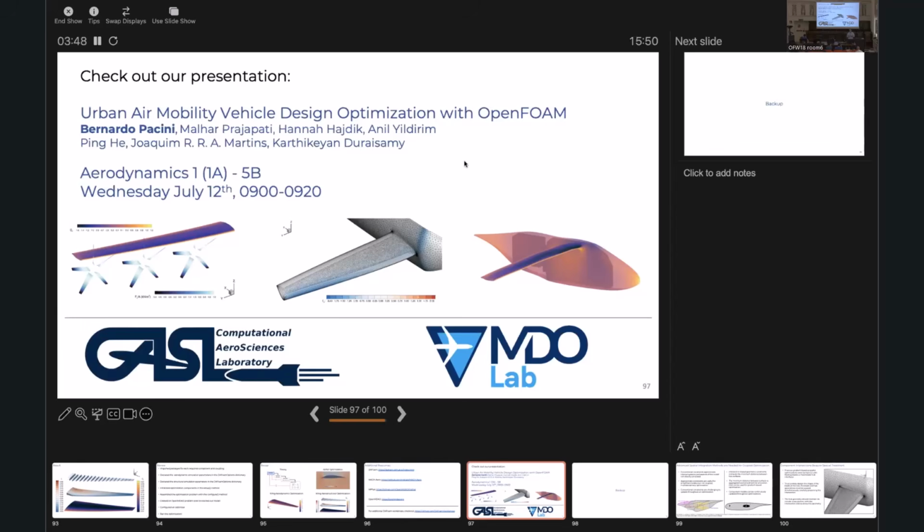I personally use Pointwise. We have a license at the University of Michigan, and it has been excellent. I know a lab mate used cfMesh, which I believe is open source, but I personally have no experience with it. And I think the previous lab mate worked with Salome. That's how you pronounce it. But I, again, have no experience with that. But I would caution against using snappyHexMesh. I think you'll run into a lot of mesh failures and a lot of frustration.